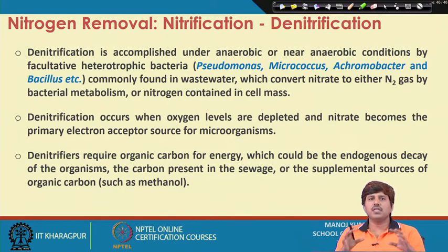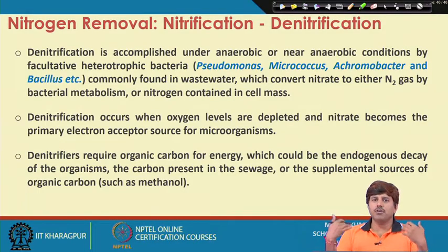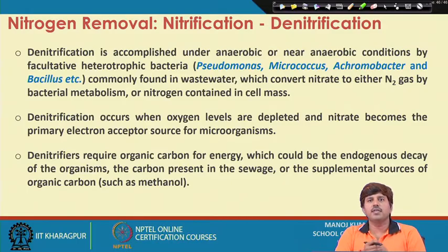This denitrification occurs when the oxygen levels are depleted and the nitrate becomes the primary electron acceptor. If there is oxygen, the process accepts electrons with oxygen, but in the absence of oxygen nitrate becomes the electron acceptor, and it is reduced further by accepting electrons.